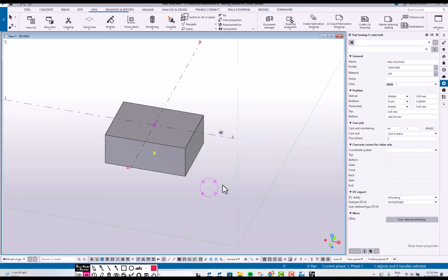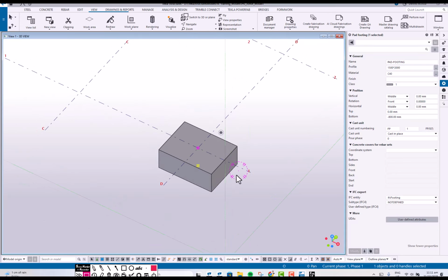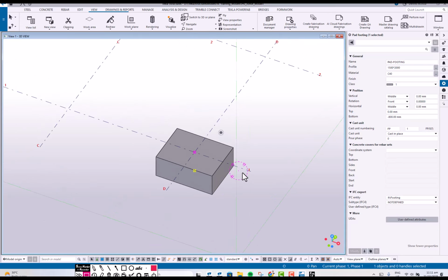Let's say, for example, there is some clashing between the rebar. By pulling the rebar, it will pull easily using this direct modification. We're going to have the practical application of that one later. Okay? But for the meantime, just turn it off, turn it on when needed. It's like I'm a doctor giving you a medicine. Okay, take it when needed.